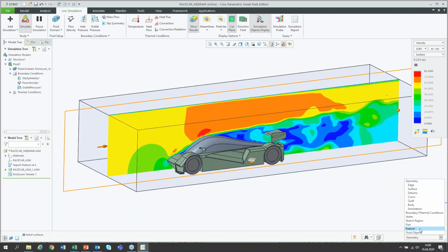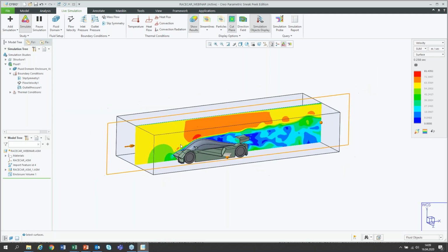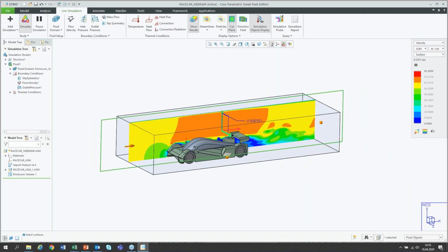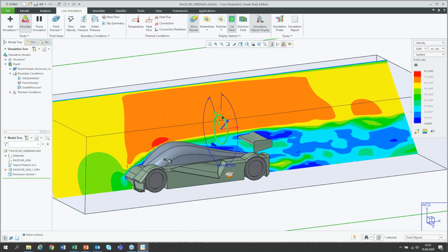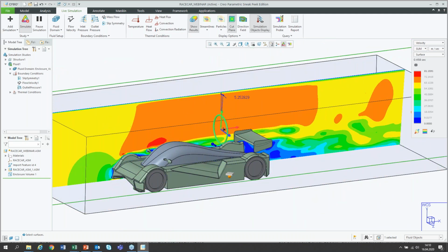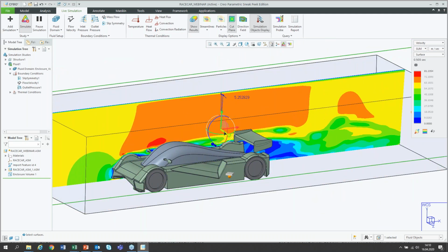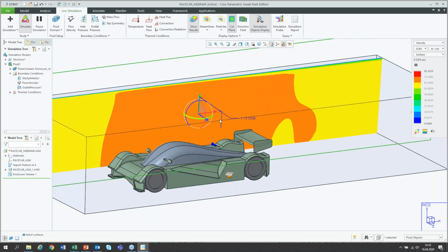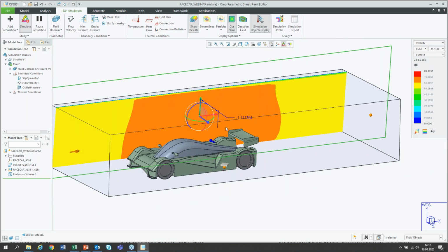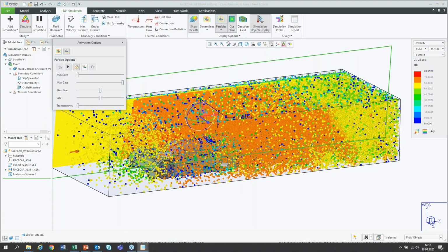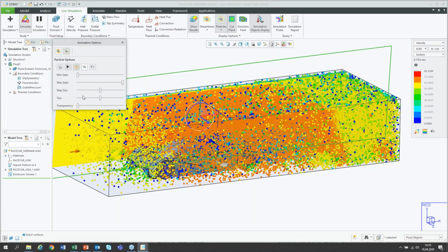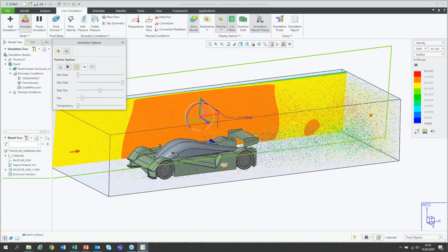Here, if I'm going to the fluid objects, by double clicking that one, I can move this cutting surface. I can rotate it. Okay, I move it back. Maybe here. Oh, this is okay for me. And I want to see right now the particles. The bubbles are too big, so I'm editing the bubble size. Maybe something like that.